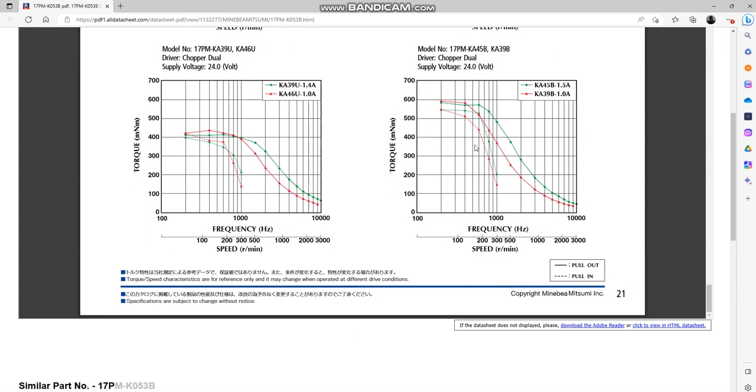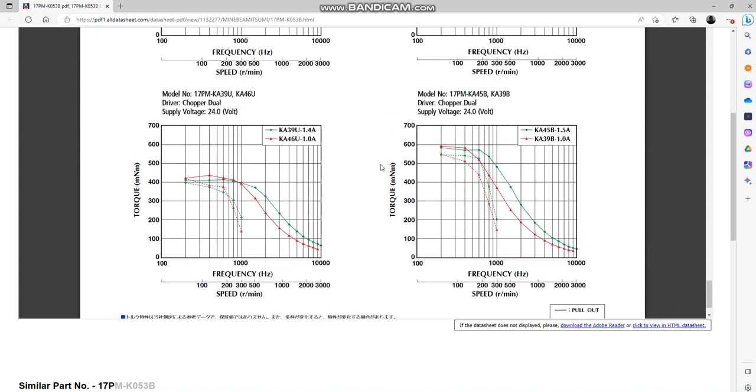So that's kind of a step-by-step process, that multi-step process that you have to follow. First, figure out the curve that you need for the respective motor that you are interested in. Find the maximum torque. When it comes to stepper motors, it would be the leftmost point on the curve, since torque starts at maximum and reduces with RPM. For a stepper motor, find that maximum torque and find out the rated current, divide the former by the latter, and you are good to go.